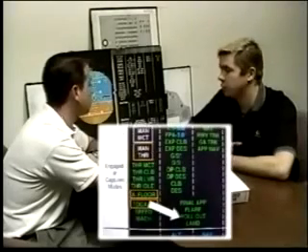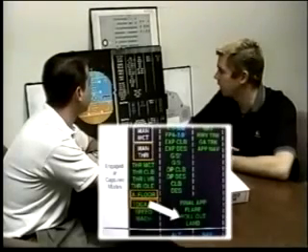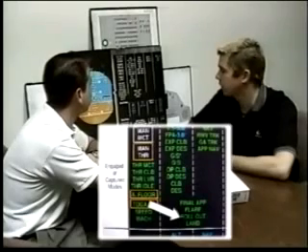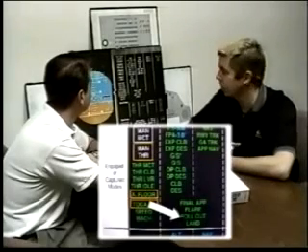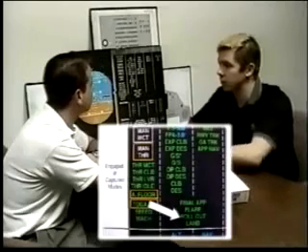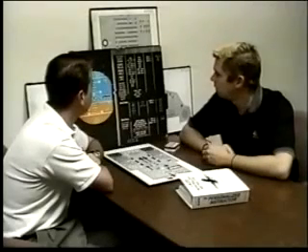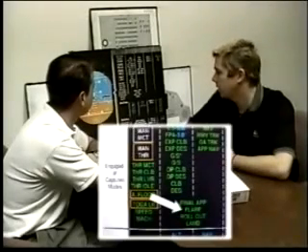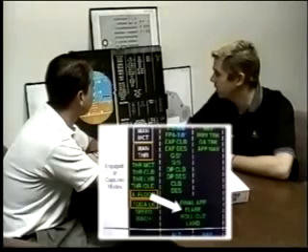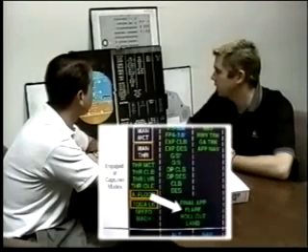What about ROLLOUT? Rollout, just after you roll out during the auto-land approach, it's basically referencing the localizer, and it's providing autopilot inputs to nose wheel steer the aircraft down the runway. FLARE? Flare occurs at 50 feet, but during an auto-land approach has to be enunciated no later than 30 feet.